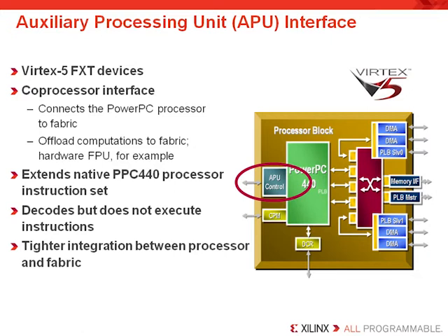The PowerPC's APU interface allows hardware accelerating co-processing to improve software and hardware co-design efficiency. This is done by having a separate port on the processor to directly access hardware on the FPGA, which would most likely be routed to the DSP slice or, say, a dedicated block RAM. Conceptually, this operates like the fast simplex link that we talked about in the MicroBlaze REL.